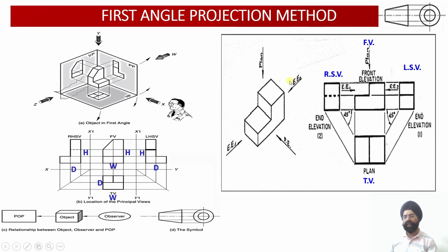But when the observer is going to look at the solid from the right hand side, please check, only one face which is lying on the rear side will be visible to the observer. So one big rectangle is visible, but this change in cross section is not visible to the observer. So when the observer is looking from this side, this flat edge of the surface is not viewed by the observer. So this edge has been drawn by the dotted line.